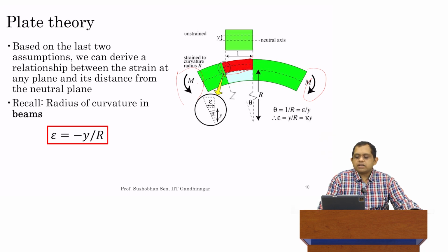Originally I have the neutral axis, and I am going to define all my directions or all my depths with respect to the neutral axis pointing downwards. This is generally how we always define it. So pointing downwards, I have the depth from the neutral axis, y. Obviously, if I'm going above the neutral axis, then my depth is simply going to be negative. So at the neutral axis, y is equal to 0, and as you go down from the neutral axis, y increases. Therefore, if you go up, y is negative.